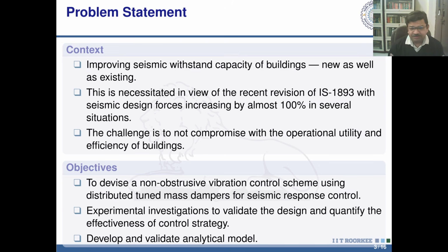For example, if we try to improve the lateral load resistance capacity by incorporation of bracings and all, first of all, it's a very messy affair, and the structural frame may not be able to take on that additional load, additional structure, and that will also compromise the functional requirement, operational utility of the buildings.